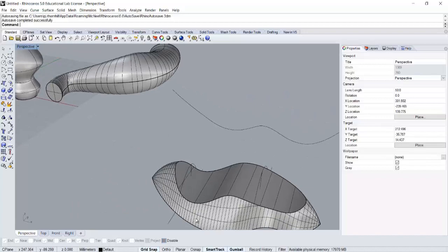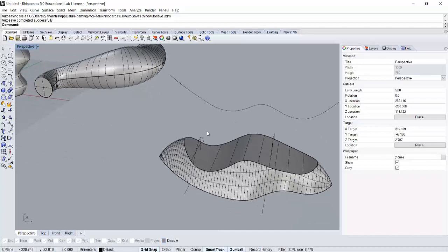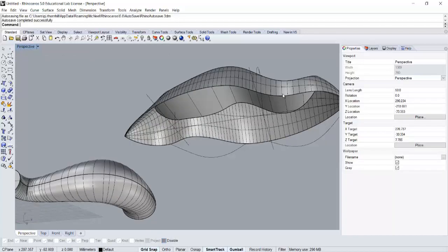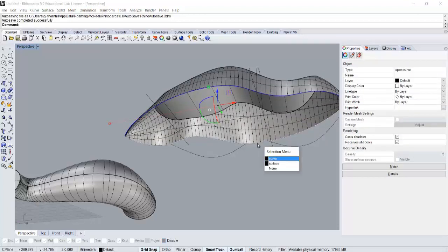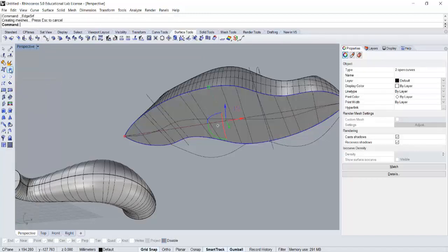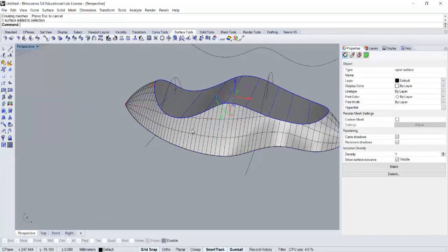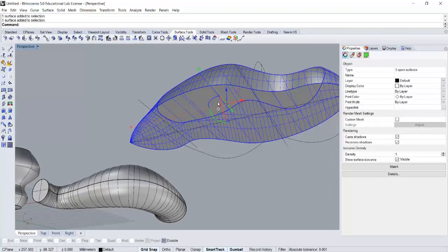So you see how that worked. I had two surfaces flowing into one another, and I used one to trim the other. If I've got two curves on the base of this, because it was a surface from network of curves, now if you remember a few minutes back, we had the option to surface from 2, 3 or 4 curved edges, so I can use that to patch that base in. And if I joined that, holding my shift to add to my selection, and again 3 open surfaces, if I hit join, I've got a closed polysurface again.